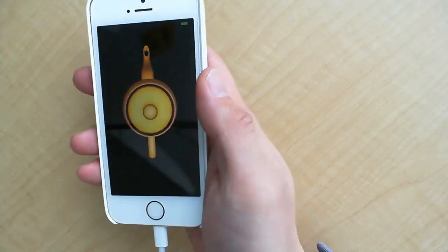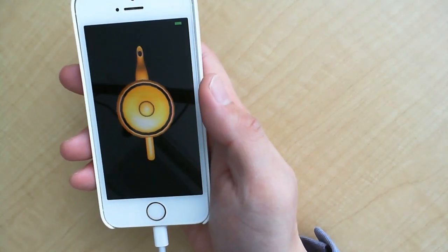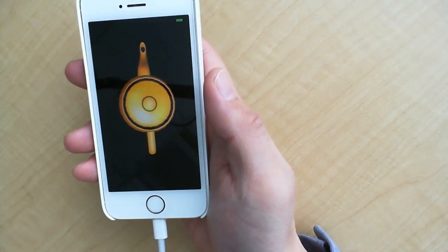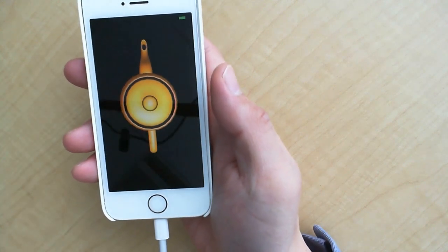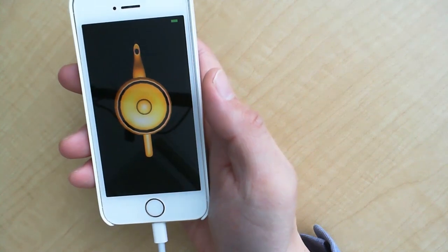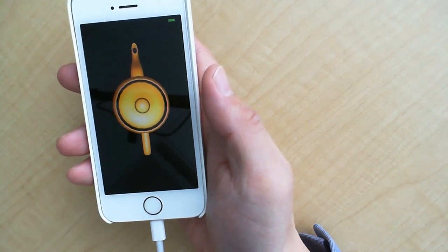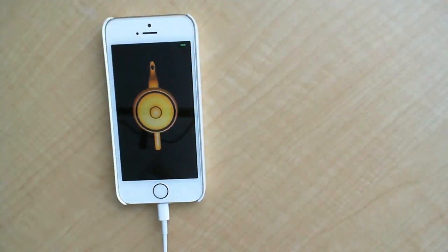So in this app, the data from the accelerometers is filtered by a simple low-pass filter before it's used to balance the teapot. We can design our own filter in MATLAB and use it in place of the default low-pass filter. So switching over to my Mac,